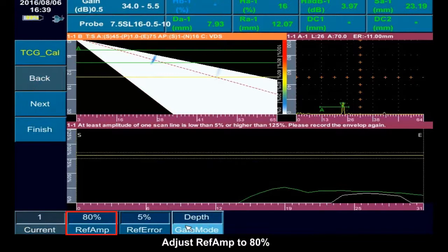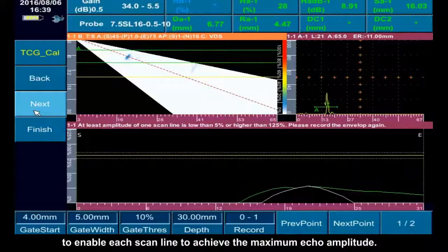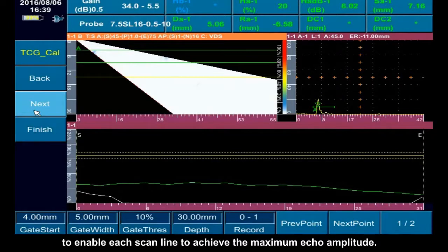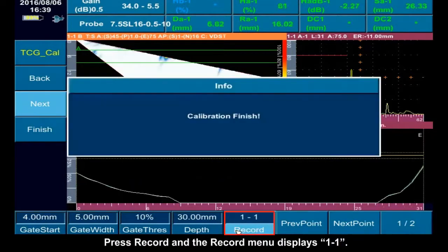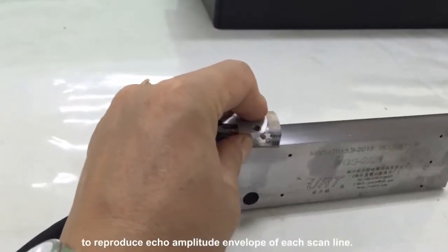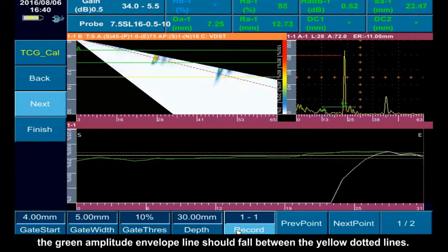TCG calibration. Adjust reference amplitude to 80% and reference error to 5%. Gain mode to depth. Press Next. Move the probe back and forth to make each scan line reach the maximum echo amplitude. Press Record, and the record menu displays 1-1. Move the probe back and forth to reproduce echo amplitude envelope of each scan line. If the calibration result is correct, the green amplitude envelope line should fall between the yellow dotted lines.